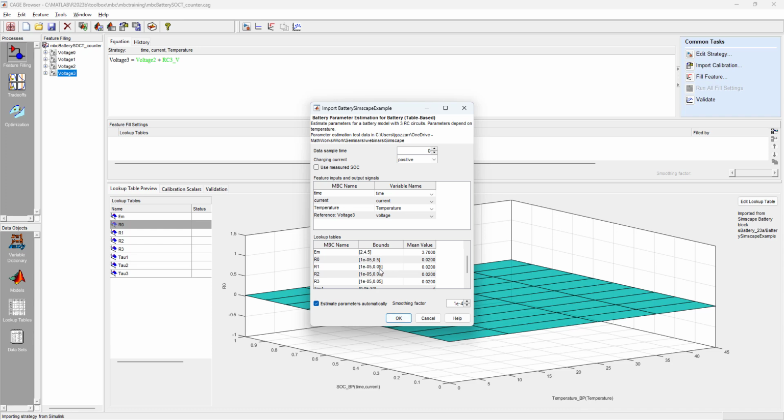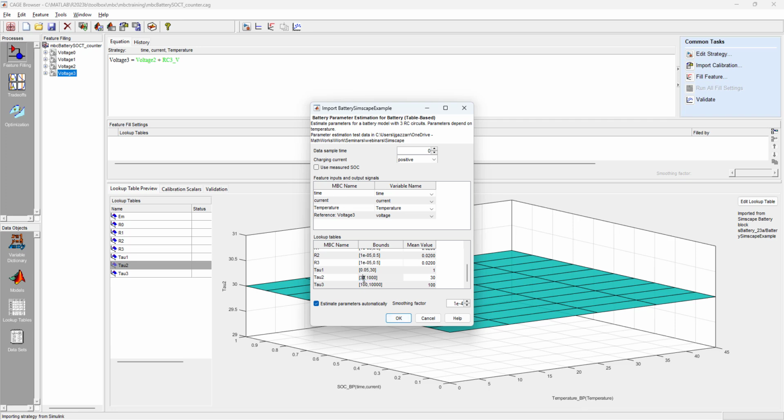Since this is mathematically an inverse problem, setting reasonable parameter bounds is useful to mitigate non-uniqueness in the results and to make sure that we're not allowing the optimizer to waste time trying parameter values that are unphysical. Our a priori knowledge of the system is useful here, for example in the choice of internal resistance ranges. A best practice when the ECM has more than one time constant is to separate the values of the time constants logarithmically.